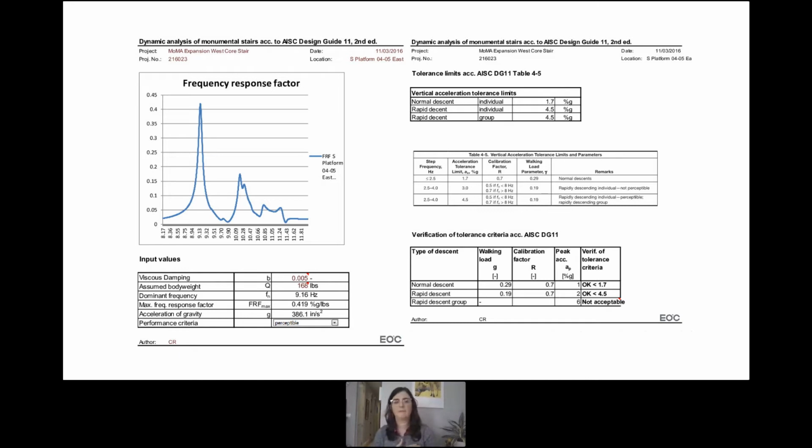And vibrations are something that it's not a code requirement, right? It's really all about what ultimately the owner is willing to accept, right? And so these are just discussions that need to be had. You say, we've done this analysis, under most, 90% of the use cases, it's going to be fine. If you have a large amount of people going down the stairs, it might get a little bouncy. Are you okay with that? And so that's one of the things that it almost never works.